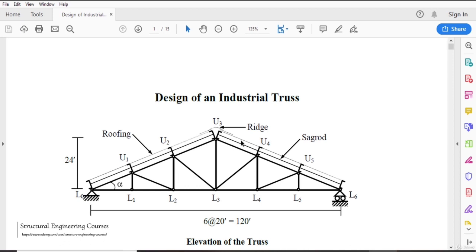That is why, if you see some cyclone or hurricane videos on the internet, what exactly happens is that the roof just blows out on the top. It is not like, when the wind comes, it crumbles to the bottom. Those failures are very impractical. In all cases of wind failures, the roof just gets blown up, or fails due to the very high suction pressure from the top.